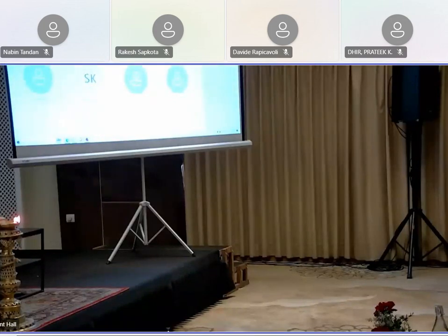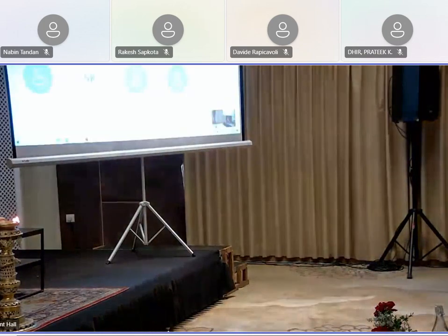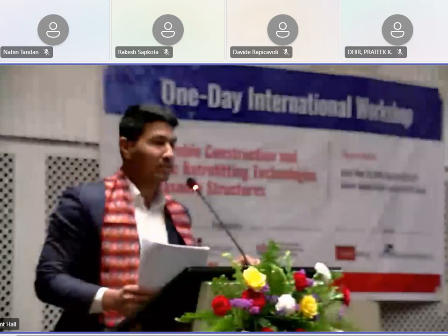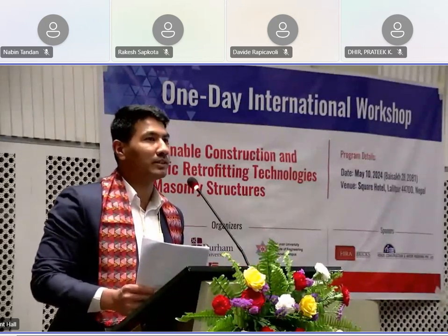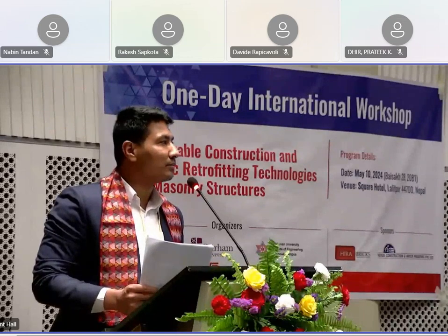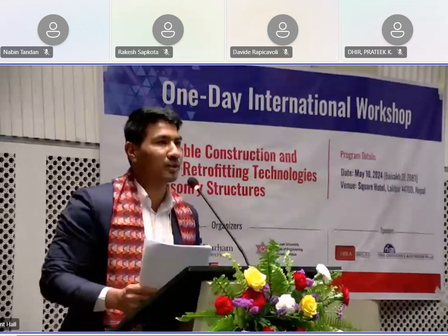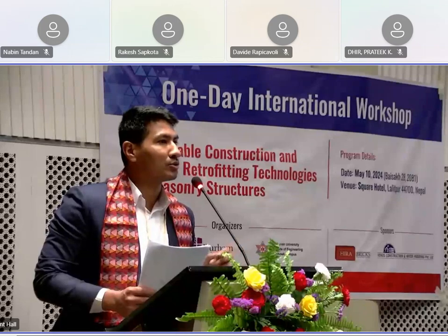Thank you, Dr. Panto, for guiding us through the whole modeling approaches in masonry. He talked about micromodeling, simplified micromodeling, and then came to macro element modeling as well, in which we have basically two categories, which he talked about: the equivalent frame method and his own model that he developed with Professor Calio, the 3D macro element method. So I think the best part about the 3D macro element method is its ability to capture the out-of-plane mechanism in addition to the in-plane failure mechanism that can be done also with EFM.